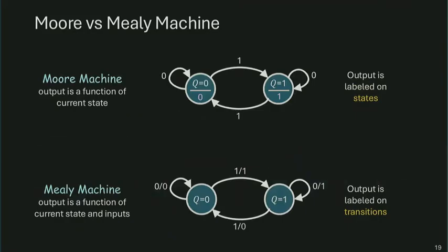All right. And here's essentially the same picture from a different abstraction level. You can also look at it in terms of the state diagram. For a Moore diagram, output will be annotated at the nodes. Essentially you put down a line and then put down some number below the state encoding, and that denotes a Moore machine. Whereas for a Mealy machine, output gets annotated next to the transitions. So a transition is triggered by some input number. And if I put an output over there, it will tell me that the output is 0 when my state is 0 and the input is 0. With some additional input information defining the output, it becomes a Mealy machine.